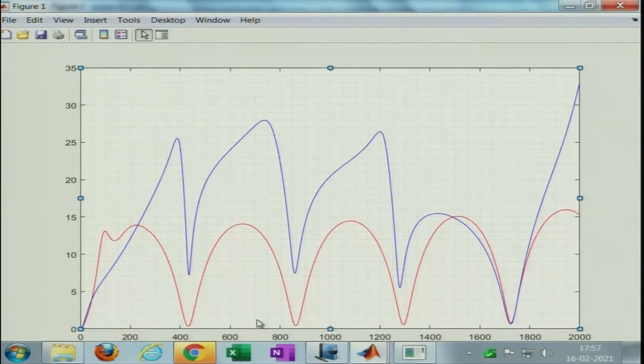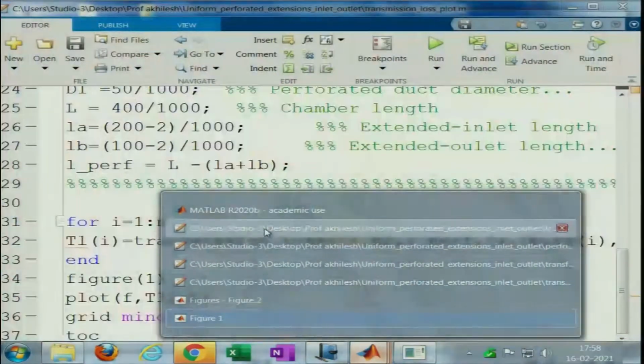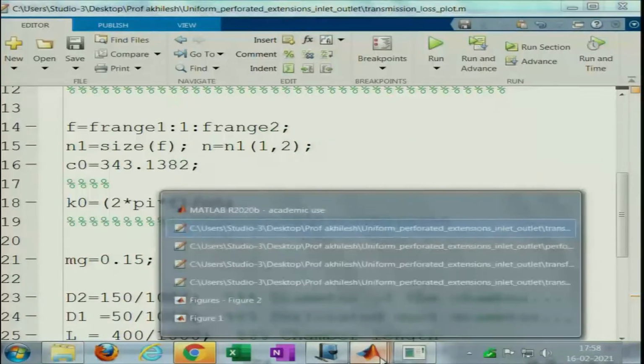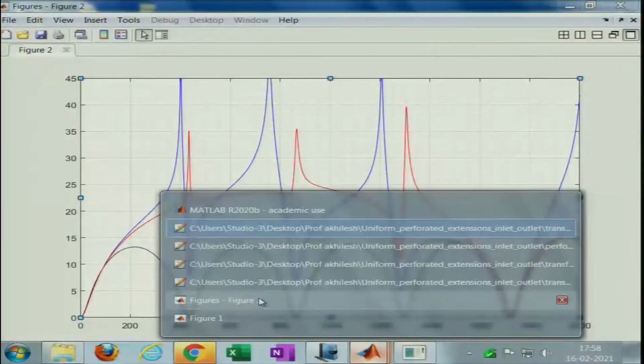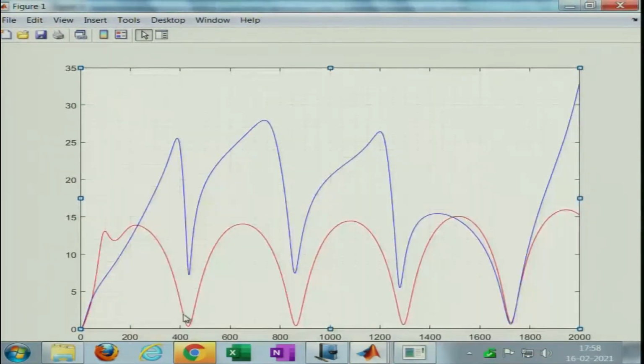But especially when you have a large porosity like the ones that we have considered, almost 30% porosity, which is like acoustically transparent, as we can see from here, 30% porosity. So, for such a case end correction will be very small. End correction really is significant when you have a very low porosity, like something less than 15% or things like that.